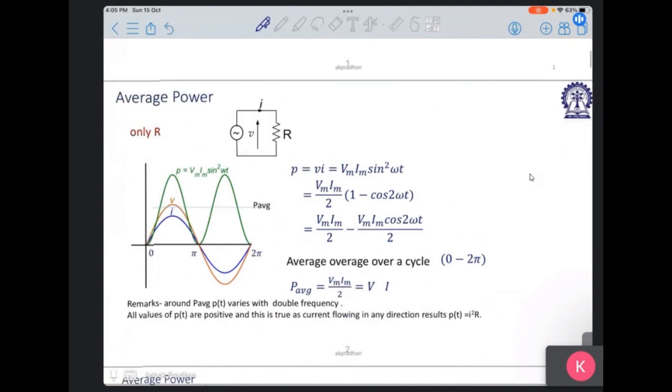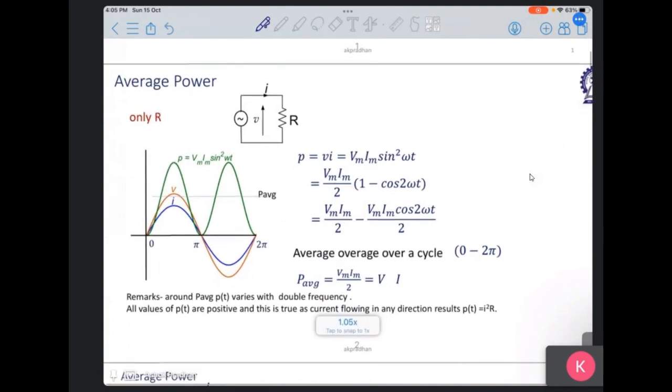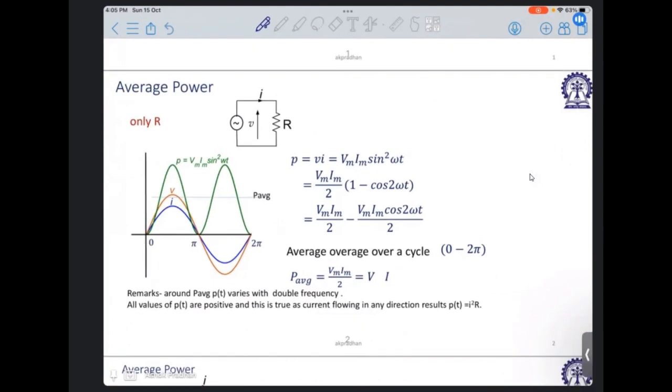When I teach in class, or you teach in class, we do the same thing. So let me start from there, because that is also associated with time domain waveforms, voltage, current. Let us say this is V, supplied by this source, and we have a resistance. So current flows, V upon R. The power associated with this is instantaneous power, V into I. If V equals Vm sin omega t, in this case this will be Vm Im sin square omega t.